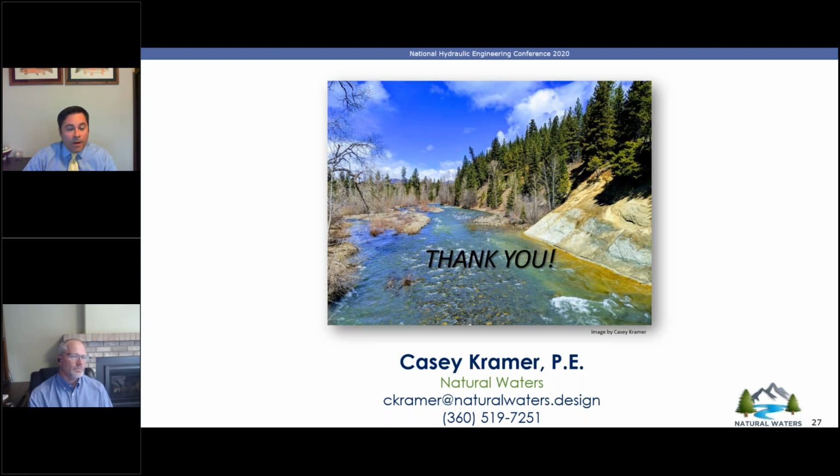To answer your question about whether you can use interpolated cross sections to create a section, my personal view is that if you're in a levied section with a prismatic channel, then yeah. If you're a surveyor out surveying and you think a typical section is representative of the ground and you're representing that in your surface, I'd say the same would be true for your 2D hydraulic model.